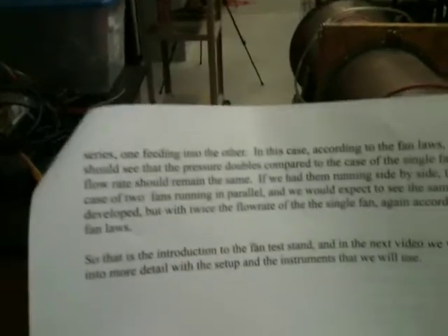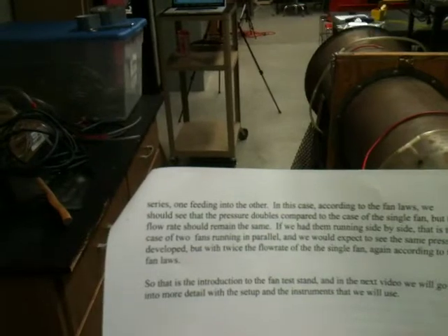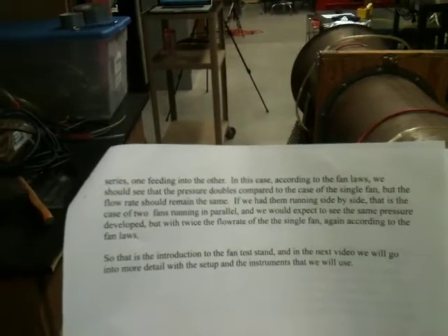So we'll have the case of 2 fans running in series, one feeding into the other. And in this case, according to the fan laws, we should see that the pressure doubles compared to the case of the single fan, but the flow rate should remain the same.